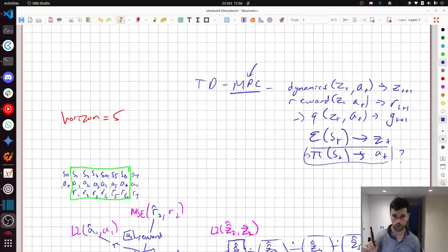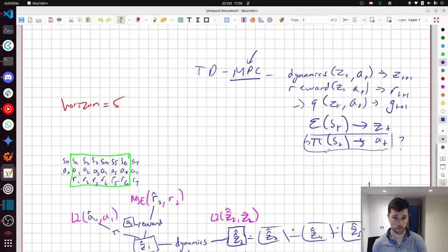And just a quick side note before I continue, this is edited in after because I realized I've raised a big question here. In the previous video, we learned about MPC and how we can use that to end up getting an action trajectory to run on our robot. But now I've introduced this policy network which predicts actions. So what's the purpose of this? Well, if you recall, when we run the cross entropy method for MPC, we start off with drawing some number of random samples from a Gaussian distribution to create proposals for action trajectories.